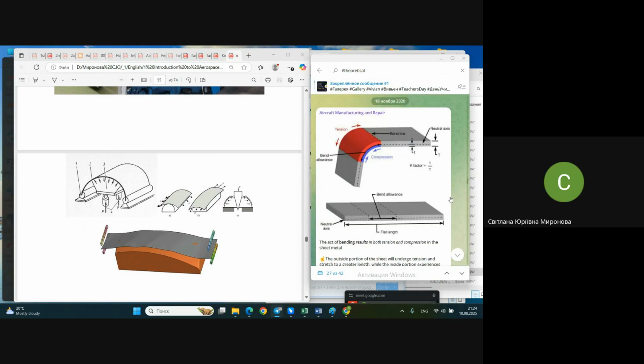Do imagine how spring back appears, because we have tension layers and compressed layers, and because of this they are trying to rotate the part back to its previous position, to reduce the angle, or in contrary, to increase the angle.